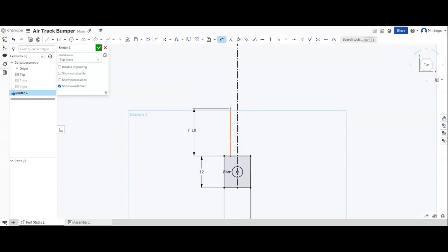Now, I also measured that the stem width is 5.3 millimeters wide. So what I'm going to do is I'm going to have the dimension tool, and I'm going to select from here to the center line is going to be 5.3 divided by 2, because it's halfway to the center line. And that sets it there, distance from the center line, and now you have your stem width.